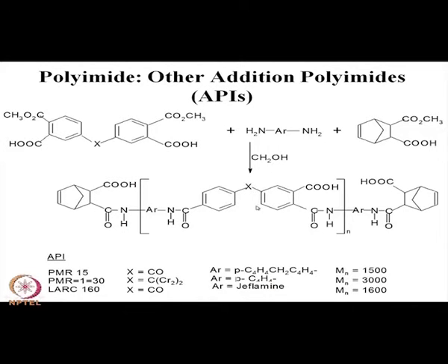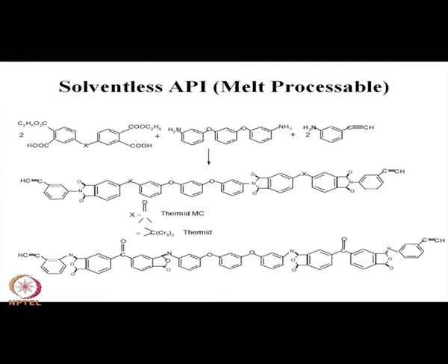So, toughness, stiffness, strength, thermal stability, all these things are tailored in the form of thermoplastic or thermoset configurations to have a broad spectrum of properties of this kind of matrix resin for making high performance composites.